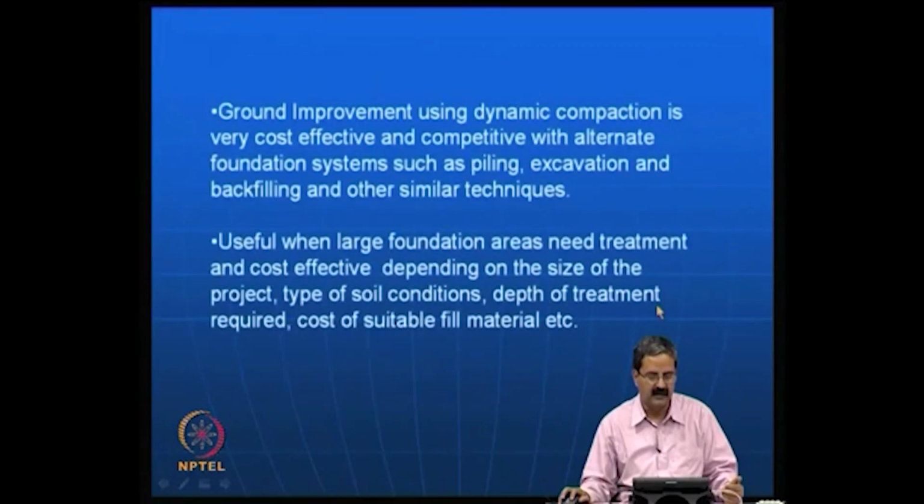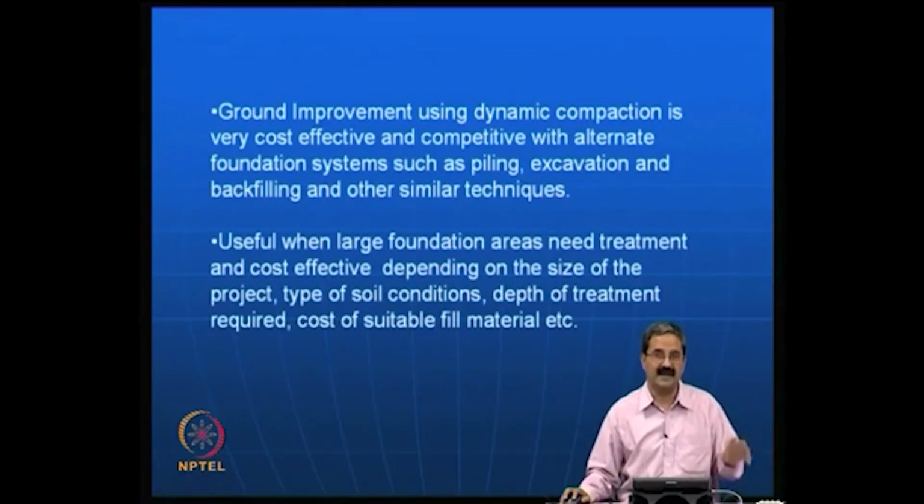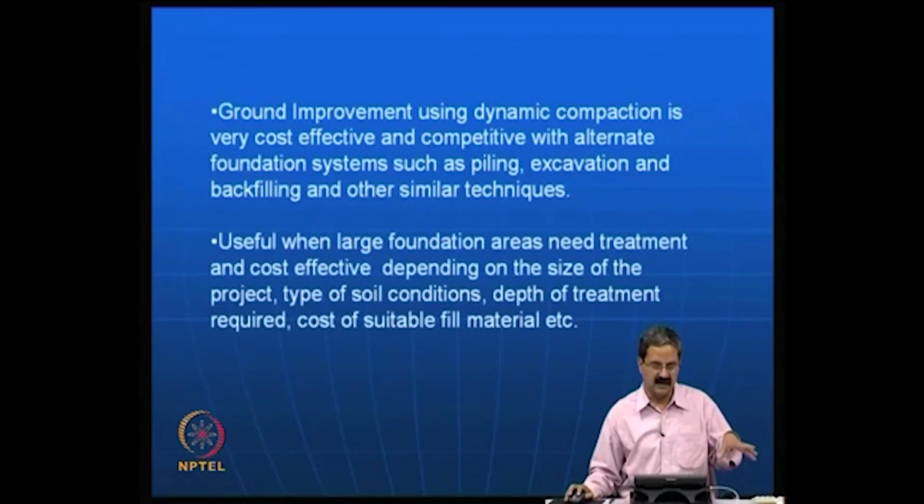That was what I meant, and particularly these people have explored a lot of other options in the site, like other similar treatments, like removing the whole soil and trying to backfill, and some of them trying to do piling. So for example, if you want to increase the bearing capacity of the foundation area, why don't you go for piles, why do you go for just simple compaction, which we do not know much. It depends on the consultant that the project has. If somebody is a geotechnical consultant, he will be able to give geotechnical alternatives, but if there is a structural consultant, maybe he may recommend piles because he has a lot of confidence.